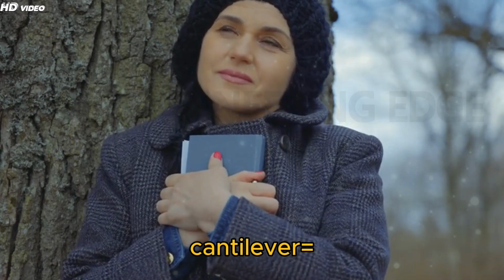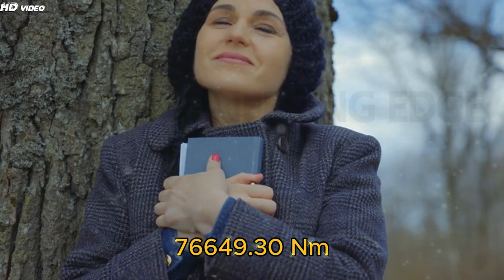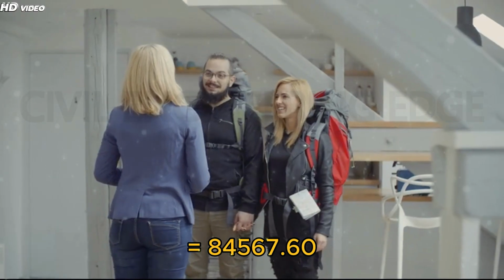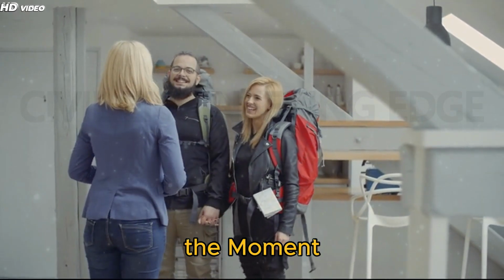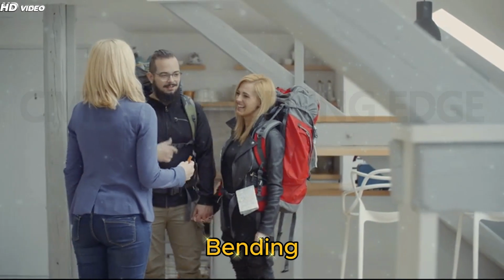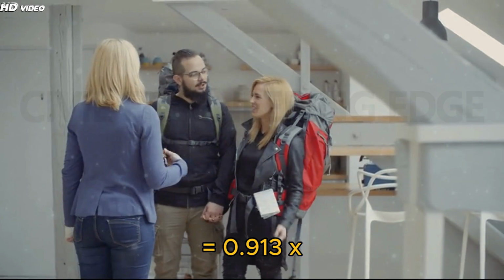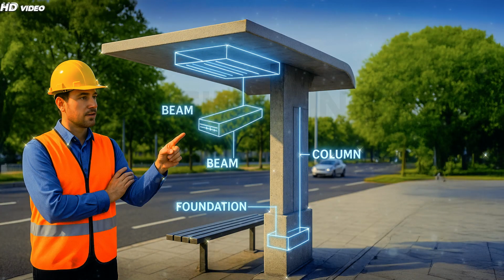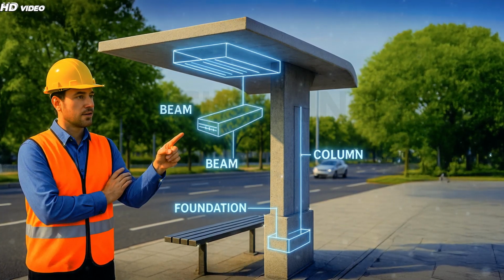Moment due to dead load of the cantilever equals 7,763 x 1.02 equals 7,918.30. Net bending moment BM equals 84,567.60 minus 7,918.30 equals 76,649.30 Newton meters. So d equals 529 millimeters.